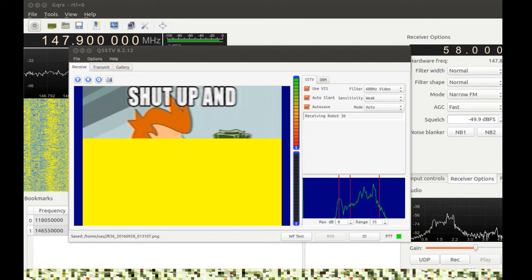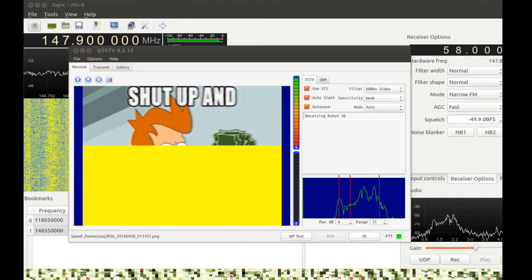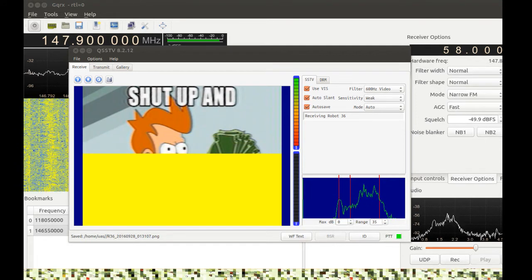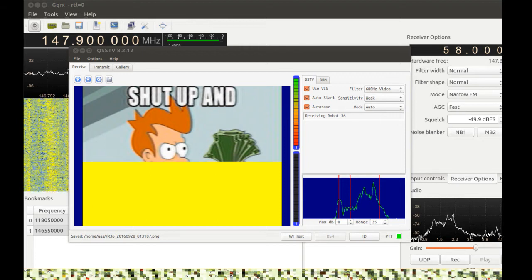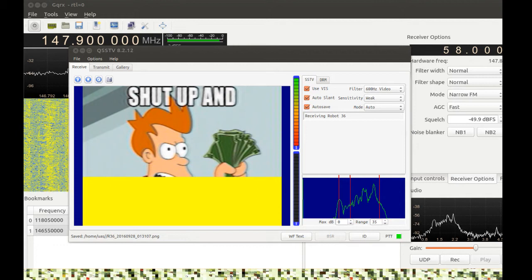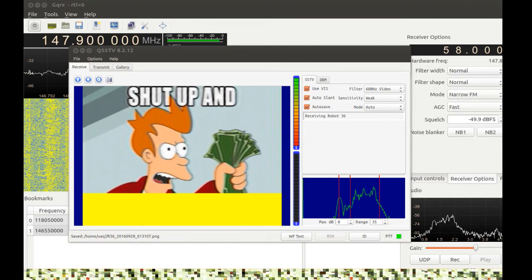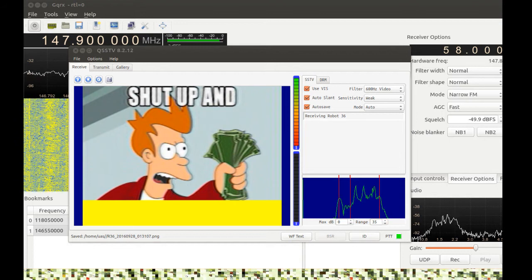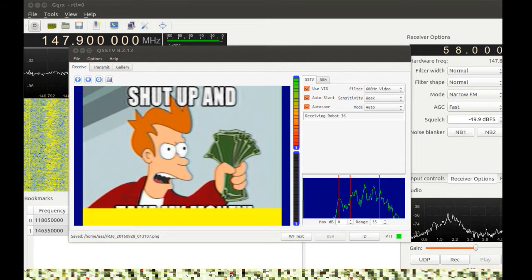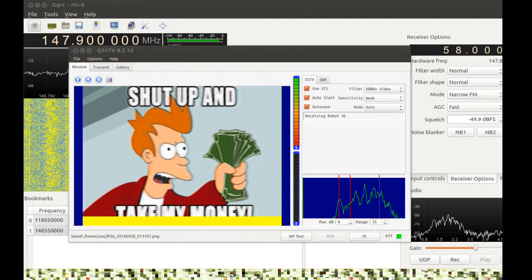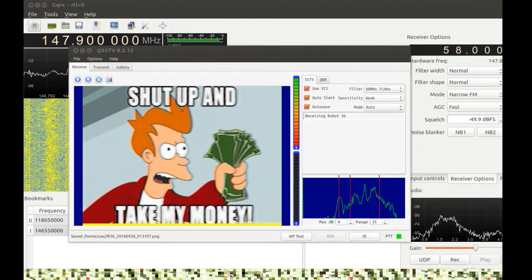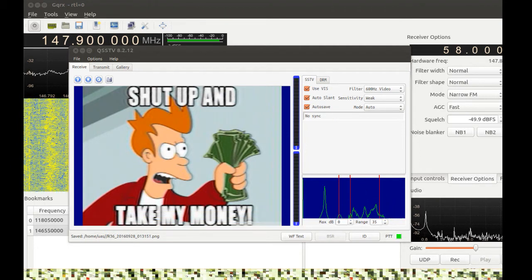Actually get it exactly on. That 16 dB, drop that down to 0 dB. I had to tune back onto it. So depending on FFT size, my center frequency is completely off. It shouldn't be that way, but it is. Just keep that on there and it'll be fine. And then open PulseAudio Volume Control. I think you're going to need to play with the levels in that a little bit.